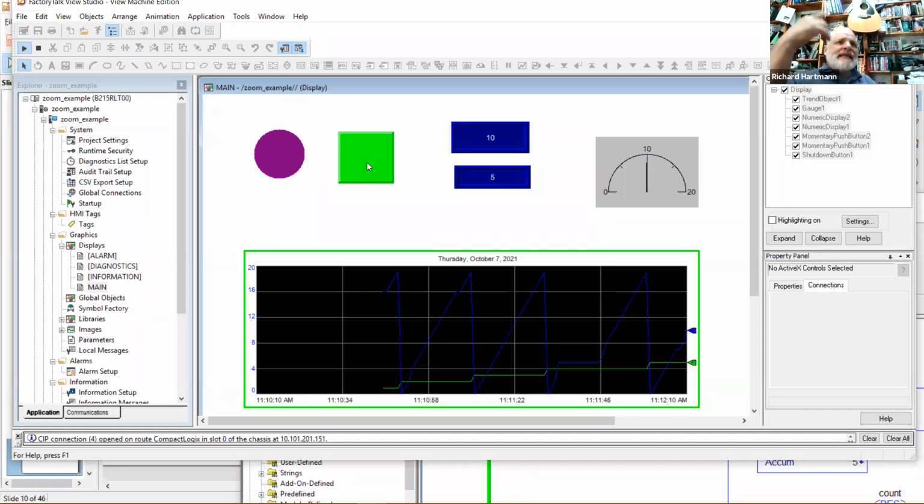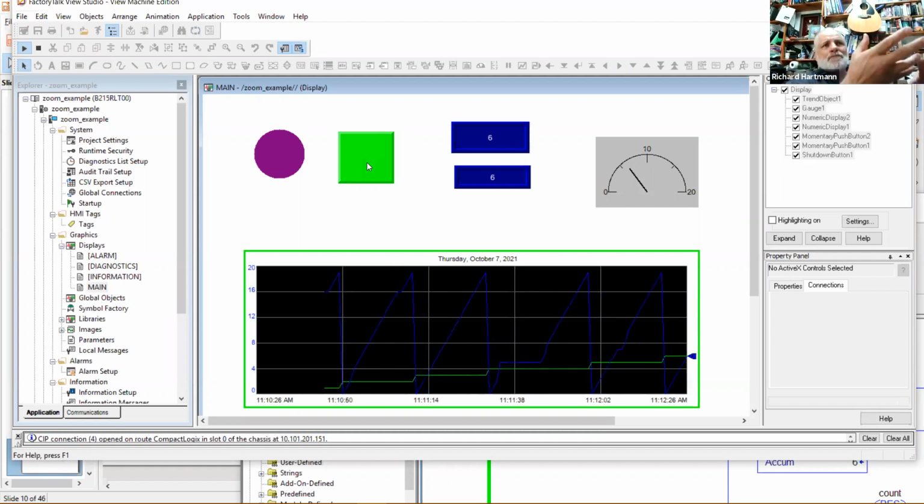Your PLC needs to be running at what we call real time. It's getting its data and it's reading in all those sensors. Every scan, it reads in all your sensors and all your inputs, and then it calculates your ladder logic, and then it sends your output.